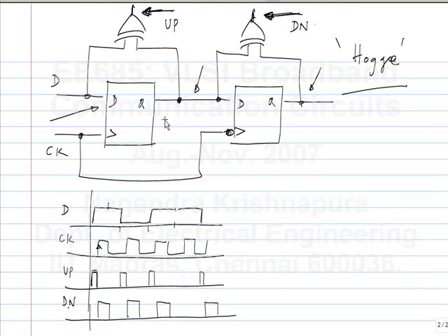Firstly, there are systems in which the range of clock frequencies is small. You know what the clock frequency is, but not exactly, simply because it's from a physically different device and it won't be exactly the same as what you produce here. So you have to ensure that the tuning range is not so much that, let's say you want to lock to 10 gigabits per second data, your VCO goes all the way to 5 gigabits per second. In fact, it's hard to make a VCO do that. So just by limiting the range, you can ensure that that won't happen.